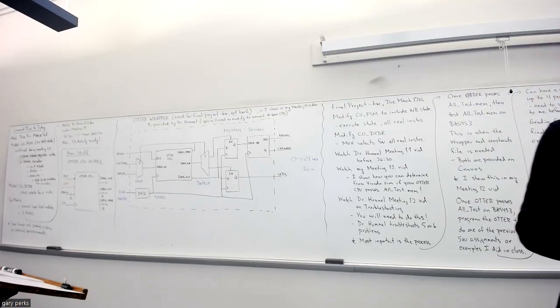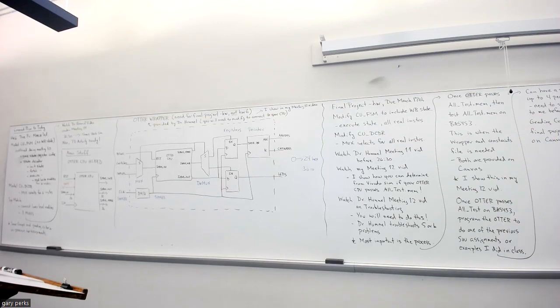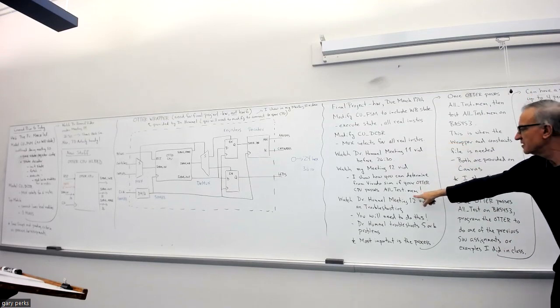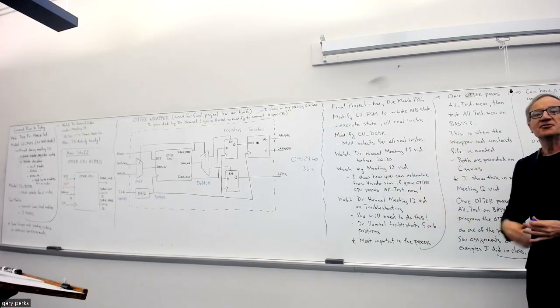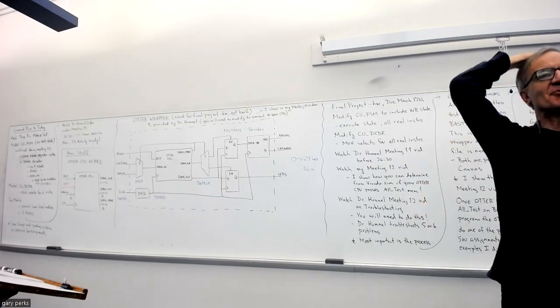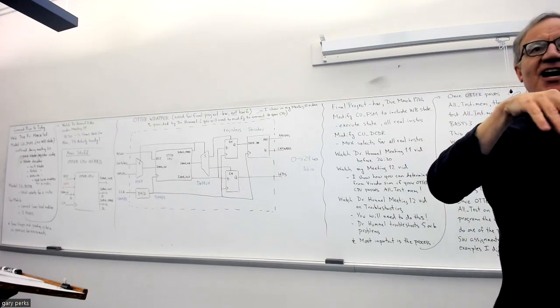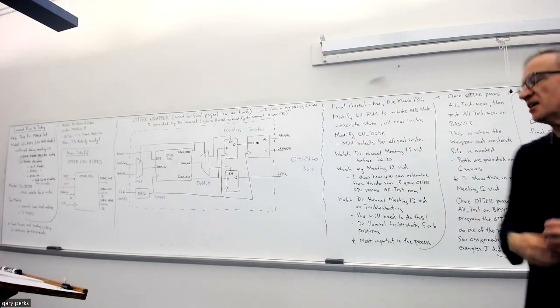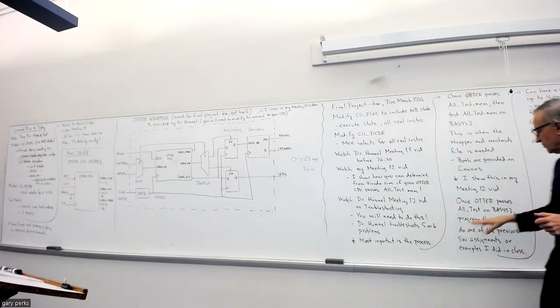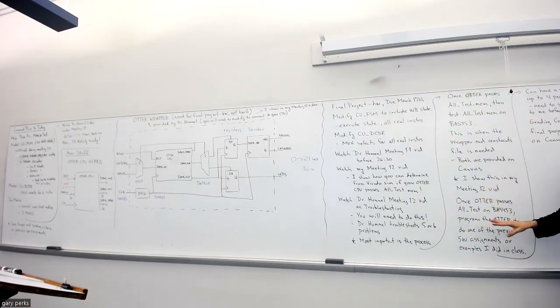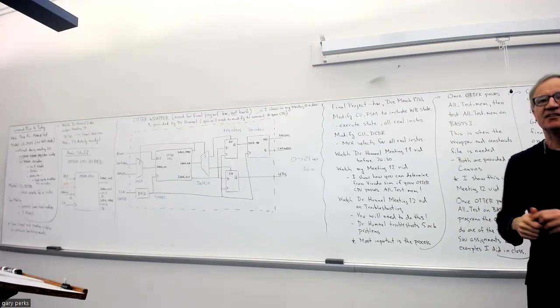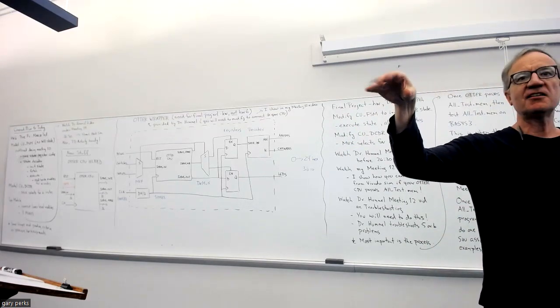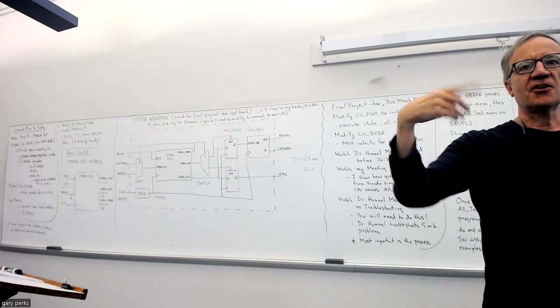Is there a way to interface RARS? Oh, right, yeah. How do we do that? The mem file. Yeah, because that was one of the first assignments. Remember, you made a mem file and then you put it in Vivado and you made sure it was running through it. So whatever program you decide to use for this, you would make a mem file and then put the mem file in Vivado, and your Otter should run that.